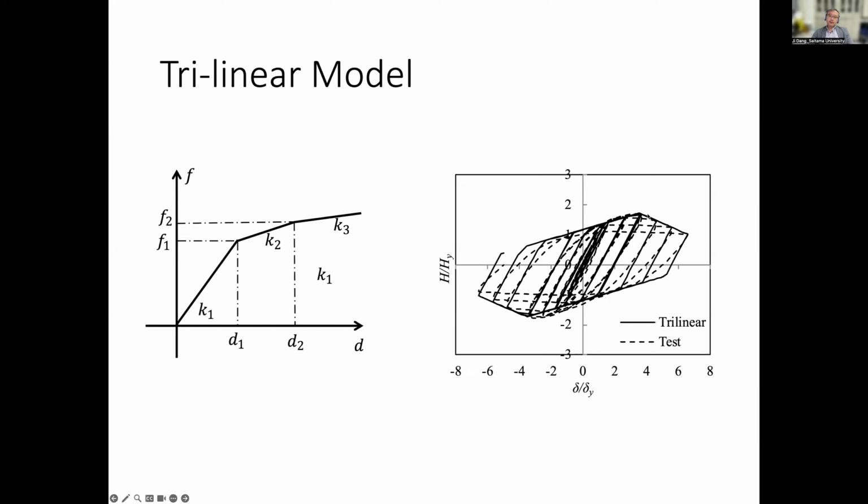For this case, they have a gradient that is lower, in the positive direction the force goes down, right? For this kind of model, we think the trilinear model is better to simulate structural hardening or softening effects, stiffness effects, like local buckling causing lowering of the force.